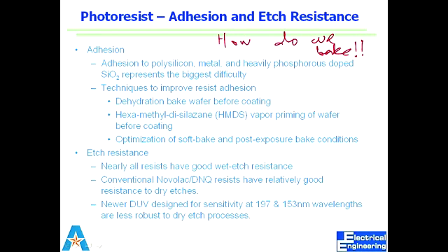What's your ambient when you're baking? Nitrogen, because you don't want oxidation to occur. Even at 90 degrees, or even if you're not heating, there's always oxidation. There's no way you can get rid of native oxide, so we live with that fact, and that's why we always do an HF dip before we do oxidation. So we start from zero. But yes, there's no way you can get rid of it. This is probably a repeat of a previous slide.